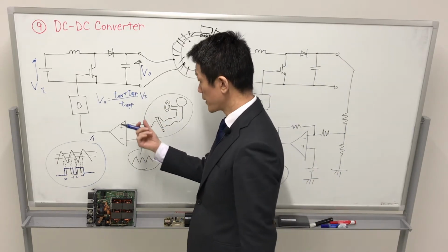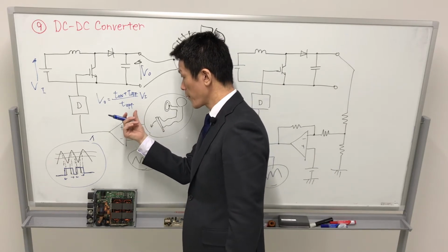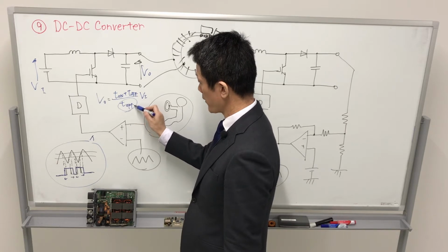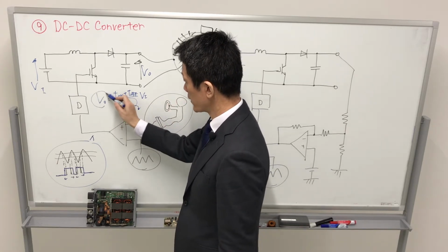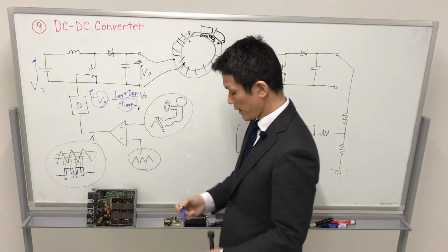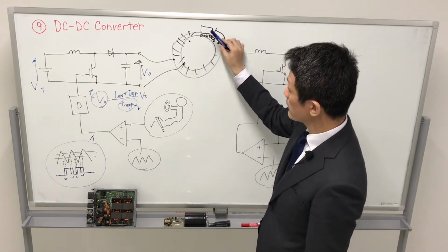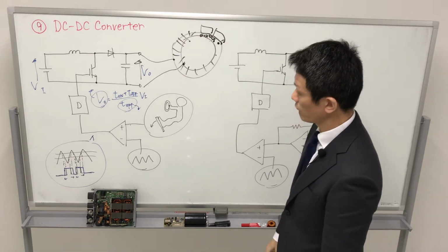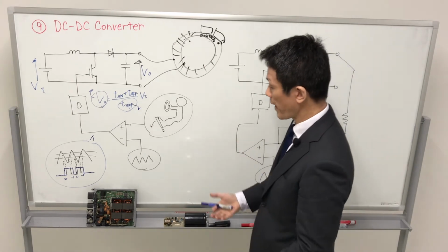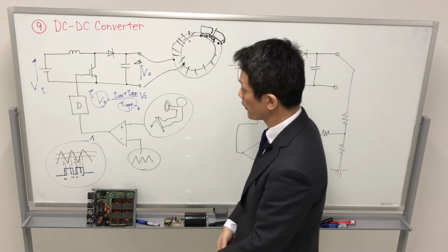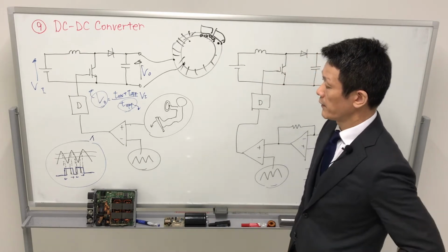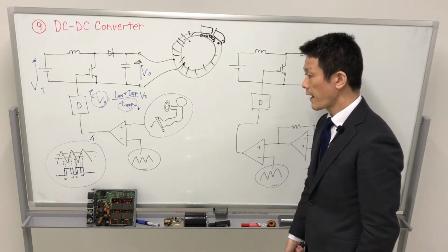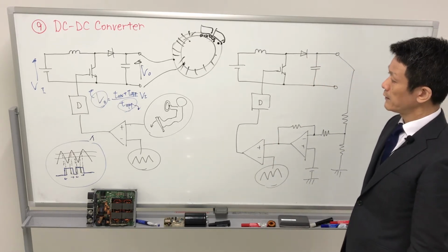So when the T on term increases, the T off term decreases, so we can obtain a higher voltage. When the output voltage is higher, the train's speed is higher. This is a very simple automotive application for power electronics axle control. Principle, only the principle.